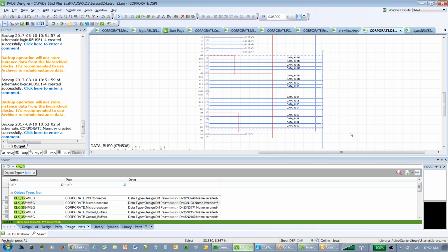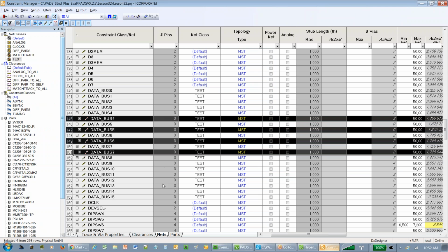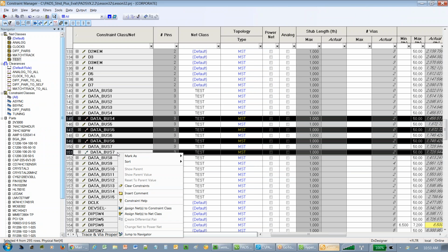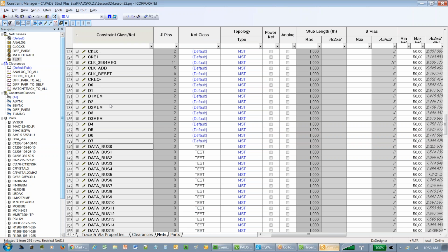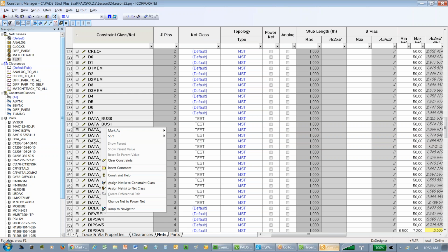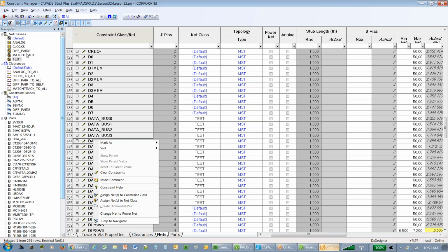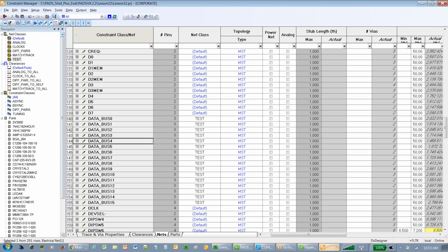You can see there again. Those nets were selected. I could group select them over here. And now if I go back over to the constraint editor, you see there it's selected all those nets. And again, you can right click. So again, very intuitive ways of doing stuff. This is one of those applications where you can hunt and peck around just by right clicking, and you can pretty much figure out how to use the application. There's not any real complex training that you'd have to go to understand how to create these. Okay.